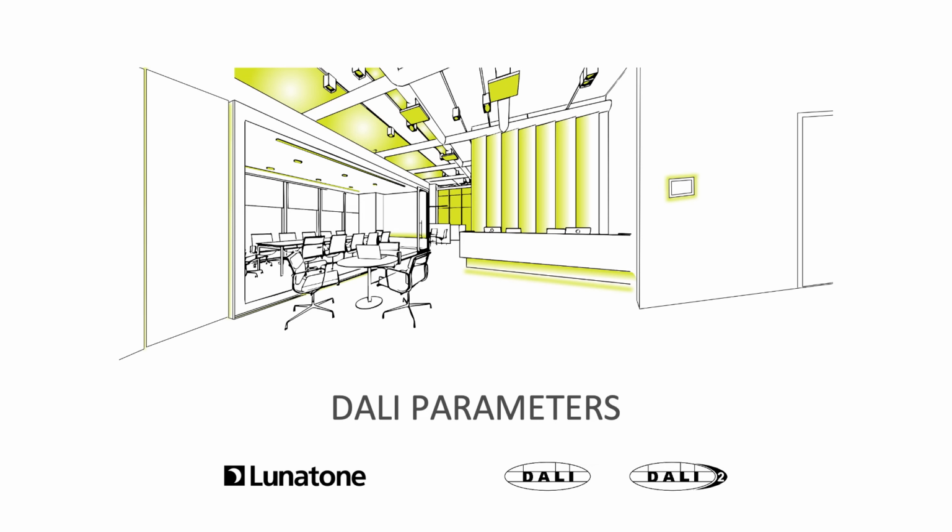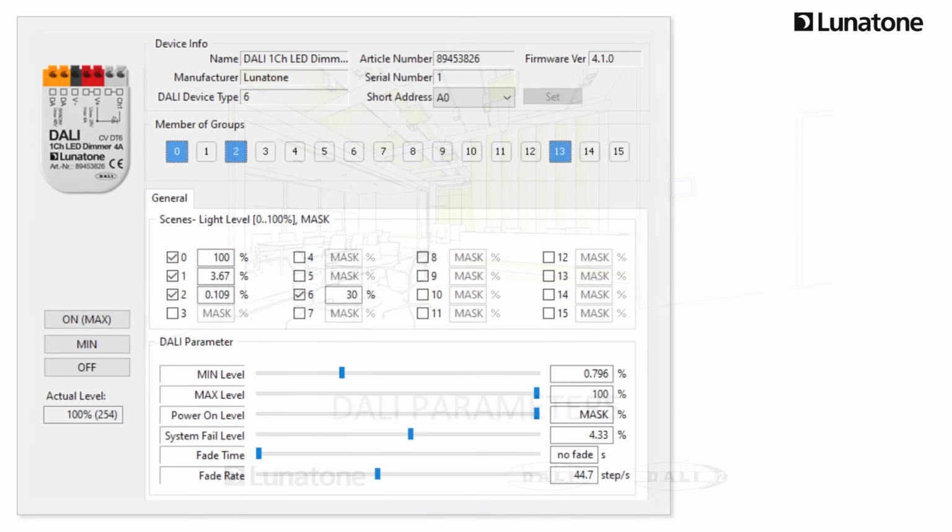We will now take a closer look at standard DALI parameters that can be set with software tools. Device type, serial number, groups, scenes, minimum dim level, actual dim level, maximum dim level, power on level, system failure level, fade time, and fade rate are the parameters for control gear specified in the DALI standard and have to be visible in the software tool. Some manufacturers provide additional information, such as brand or device description, but that's up to the manufacturer. Let's have a look at these parameters in the Lunatone cockpit software.